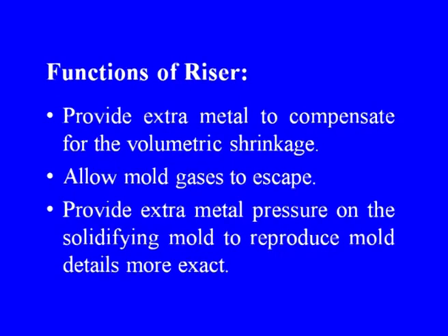Now, let us see the functions of a riser. It provides extra metal to compensate for the volumetric shrinkage. Then, risers allow mold gases to escape. They provide extra metal pressure on the solidifying metal to reproduce mold details more exactly.